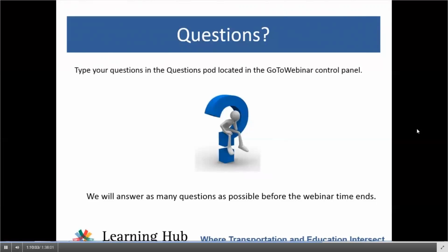And there's other ways to synthesize the OD method. There's actually in volume 4 in chapter 34, there's some guidance on how to do that. It's not unlike what I think many times we would do an analysis for an interchange, even a traditional diamond interchange. We would first develop OD volumes, and so there's a few different ways to do that.